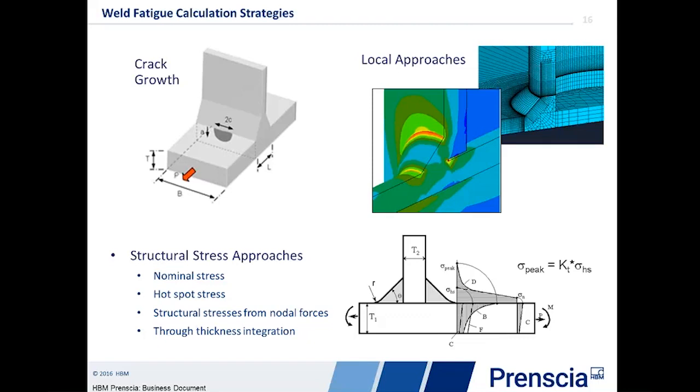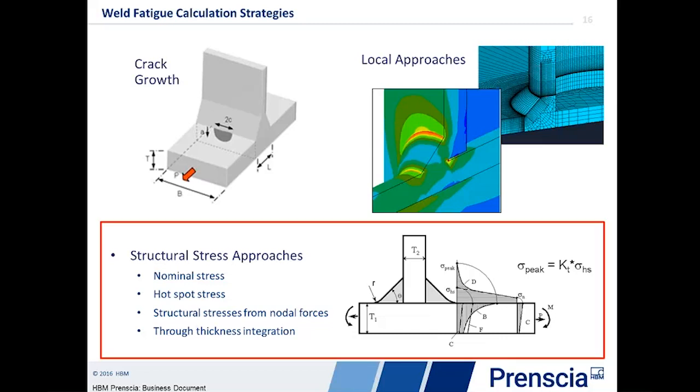This has some benefits in that we're able to go in and more closely describe the weld geometry and things such as the weld reinforcements, the penetration amount, but typically when we look at these, they tend to be very much looking at a cross-section of weld. They don't have applicability typically to things like weld ends, where we normally see issues. So there's a third approach, a structural stress approach, and that's actually what we'll be looking at today.